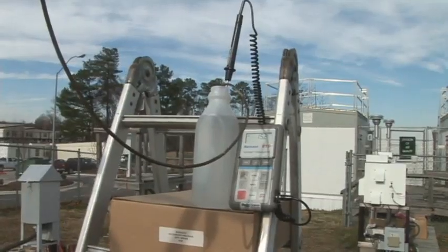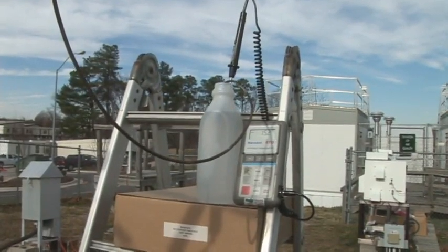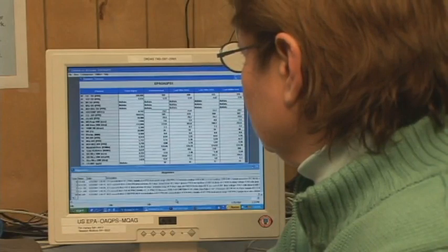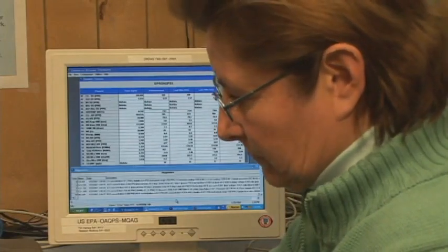After the thermometer stabilizes, the outside technician records the value from the thermometer. The inside technician records the DAS reading as well. If the responses to the calibration are within the specifications for your program, then the sensor or DAS do not need to be adjusted. If adjustments are made, it is recommended that you rerun the calibration points with all 3 water baths to reaffirm that this is true.